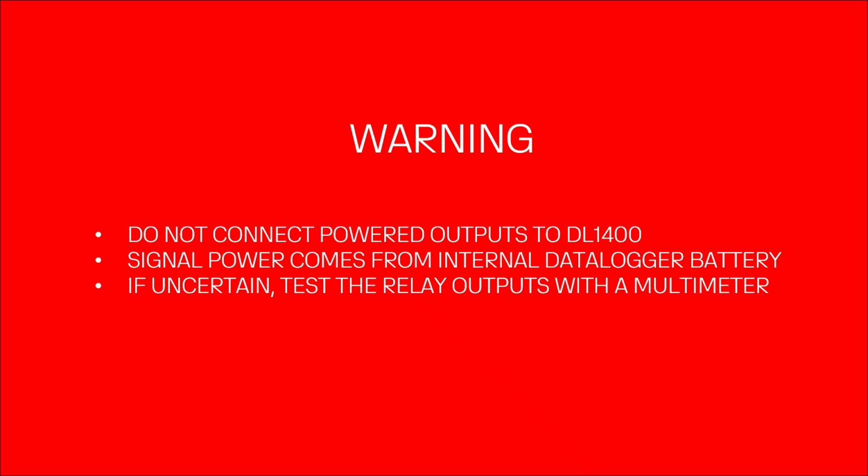So here's a warning, which is do not connect powered outputs to a DL1400 data logger. This is because the signal power comes from the internal data logger battery. If you drive power into it, you're driving power into the battery, and you can actually, in the extreme case, cause a fire because you're throwing a lot of energy into the circuit and overloading the data logger.